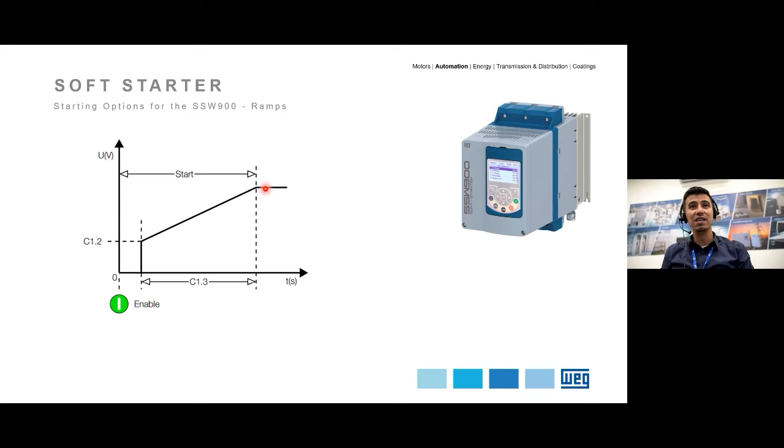We pretty much do the same by varying the voltage. You're giving less torque when starting at low speeds, and then as soon as you accelerate and increase the voltage ramp, you're giving more torque to the application. And if your demand is high as well, you pretty much follow what your demand is, right?